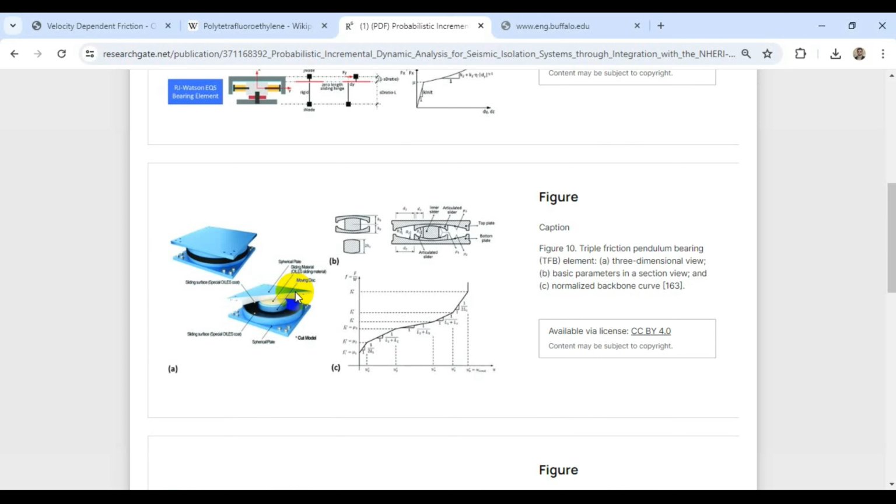The first one is the low friction across a range of speeds. And the second, which is very important and related to the friction model, is the self-lubricating properties. So, unlike some materials with friction that increases or decreases significantly with velocity, the PTFE offers a relatively low and stable friction coefficient across a wide range of speeds.